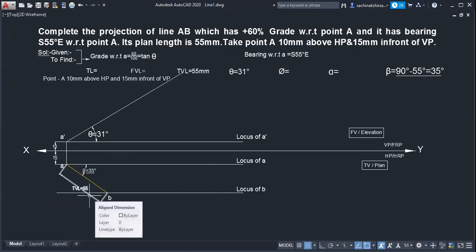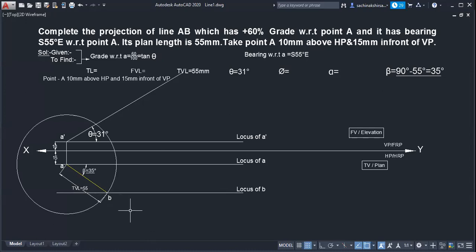Simple question you have to mark. Which length is with you right now? Apparent length or true length? Apparent length is with you. So from this, if you want to find true length, how many times have I told you? From apparent length you make true length: rotate and straight. You have to rotate, then go straight. At this stage, you should not make this simple mistake. Which length will you get? True length.